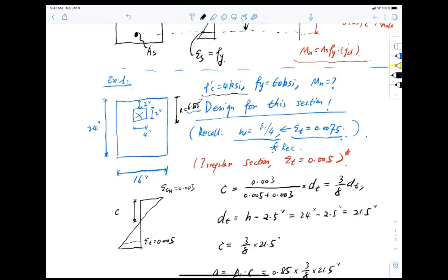So what is the promise I was given to utilize ds minus half a? We need the stress block, right? What does the Whitney stress block say? It says that within my territory, the stress is uniform. Every point I see a 0.85 f'c, isn't it? That's the promise Whitney told us, right?